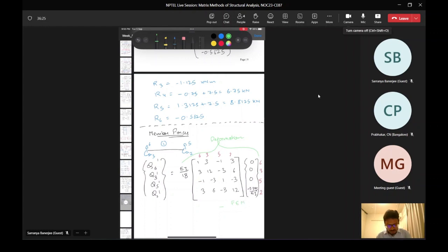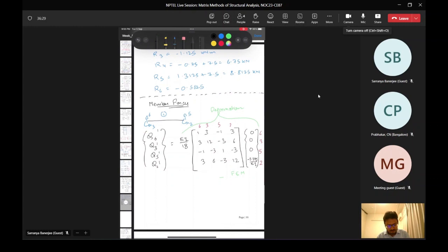So for the fixed end moment, in this case, it was all 0 for the first beam, right? So in this case, it is fine. You can just find the internal forces coming from the deformation. But in the other cases, it will not be fine, right? Is this concept understood, that we also have to subtract the fixed end moments?